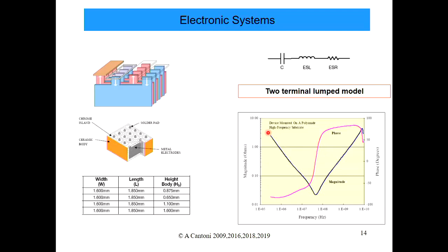J omega C, right? So this is a log plot, so it should look like a straight line, right? Because it's 1 over J omega C. So it's good. But then it gets to a point where it reaches a minimum, which is pretty low, but then it starts increasing again. Okay, and what is the component whose impedance increases with frequency?